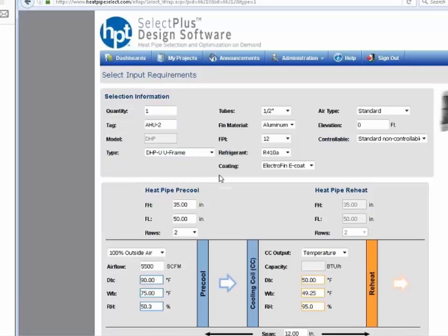The U-frame is a fully installed or a fully enclosed wraparound heat pipe, similar to the picture you see here on the right, which we ship to the customer or contractor or air handling manufacturer at their factory to slide into their unit when they're essentially installing the air handler, building the air handler. So it's fully enclosed, fully charged, ready to ship and slide right in.